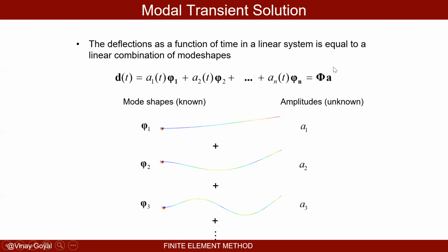But say I model this beam with 1,000,000 degrees of freedom. Anytime I apply a forcing function, maybe not all the modes participate in the motion. Perhaps it's going to be maybe the first 10. In fact, the more complex the mode shape, the less likely it's going to really take that shape in real life. So what I could say is, what if I truncate? I don't use all the modes to determine the deflection of that beam. That could be a perfectly good assumption.